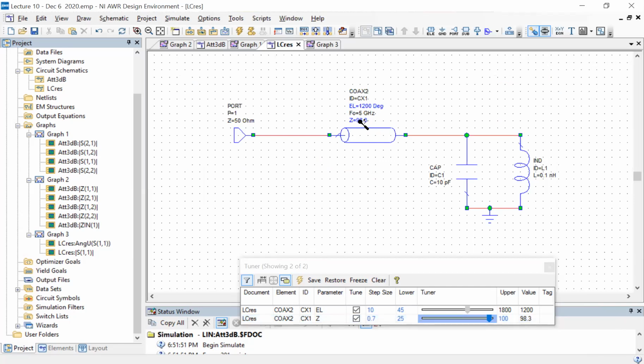What ends up happening is that this is actually still 50 ohms, but the connections of this cable to this resonator and this cable to the 50 ohm port could have some reflections, like the transition I was just showing you from the book. And that can also make this entire section of the transmission line into a resonator. And then the response of that resonator is going to ride on top of the actual reflection coefficient you are interested in. Okay, so these are two different kinds of problems. One is just a deterministic phase wrap. The other one is also deterministic, but you will not usually know the properties of this thing to be able to undo this. Okay, it's not so easy.